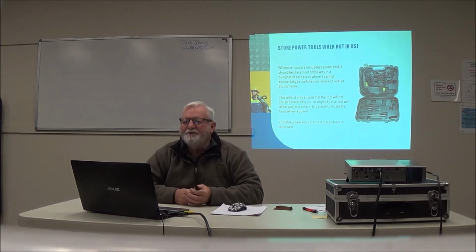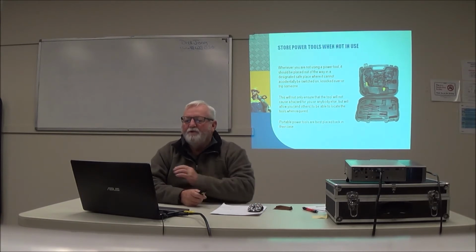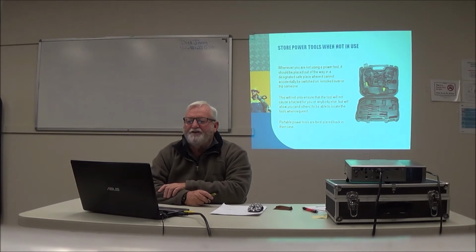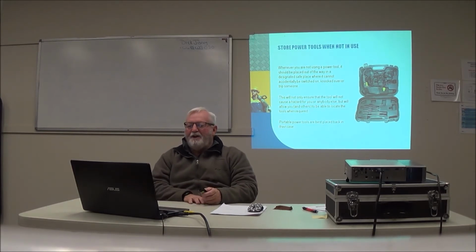Storing of power tools when not in use. When you are not using a power tool, it should be placed out of the way in a designated safe place where it cannot accidentally be switched on, knocked over or trip someone. This will not only ensure that the tool will not cause a hazard for you or anybody else, but will allow you and others to be able to locate the tool when required. Portable tools are best placed back in their case.